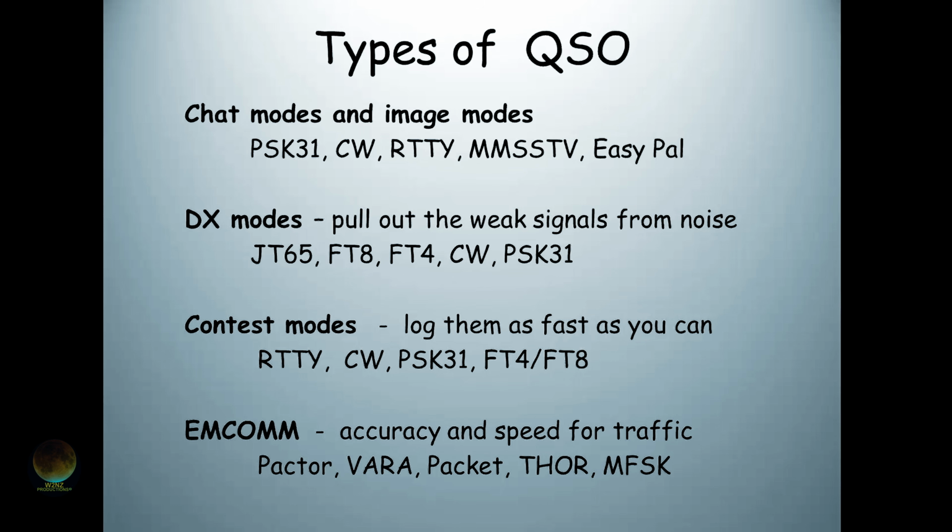Emergency communication, the EMCOM modes. I've gotten more involved in this in the last 10 years of my life. What's important here is accuracy, accuracy, accuracy, and to some extent speed. So we don't pick up microphones when we're on EMCOM duty and start talking about what we need. And I certainly wouldn't get on CW with my CW skills to send emergency messages at my stage of life. But the EMCOM modes: PACTOR, a great international emergency communication mode. Vera is a new sound card mode. Packet has been around for years and years. And among the HF modes, they're usually THOR and MFSK for emergency traffic.